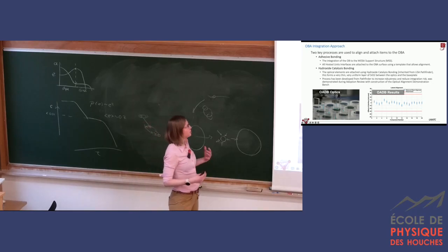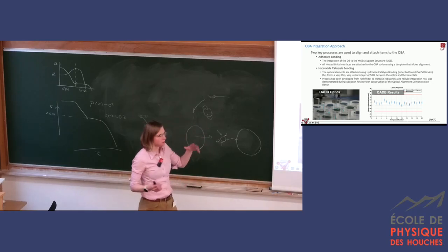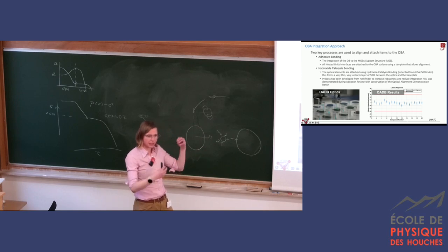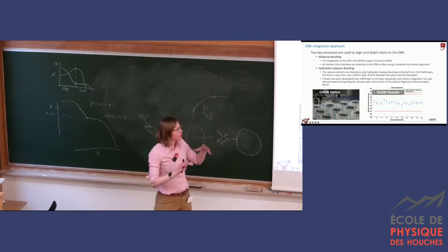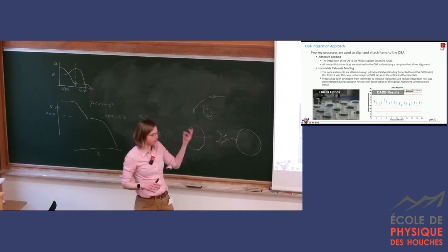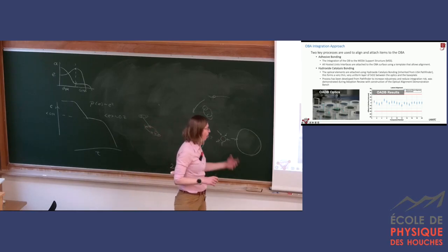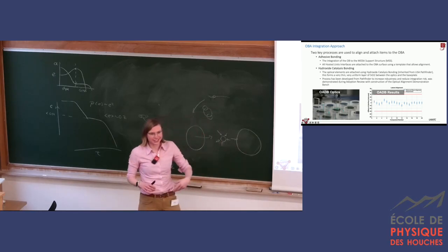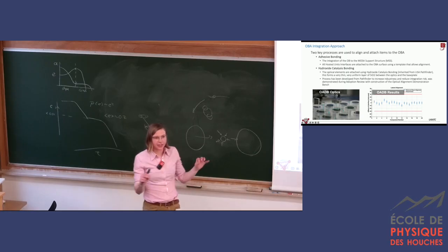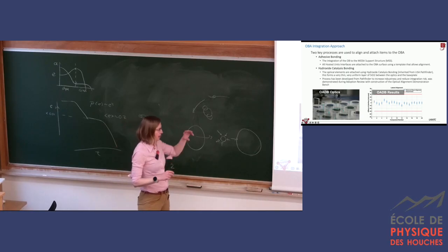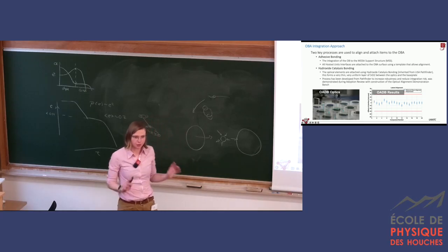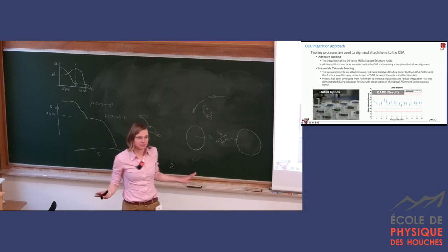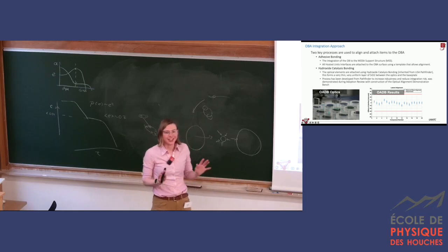There are 2 methods used here: adhesive bonding, which is mostly used for the lightweighting insets combined with the MOSA structure, but all of the optics is bonded via hydroxide catalysis bonding, which creates a thin layer of silica between the optic and the optical bench. Then the problem is that you have only 2 minutes to do it. After 2 minutes, it cannot be undone. So you can see the pressure on people doing it.